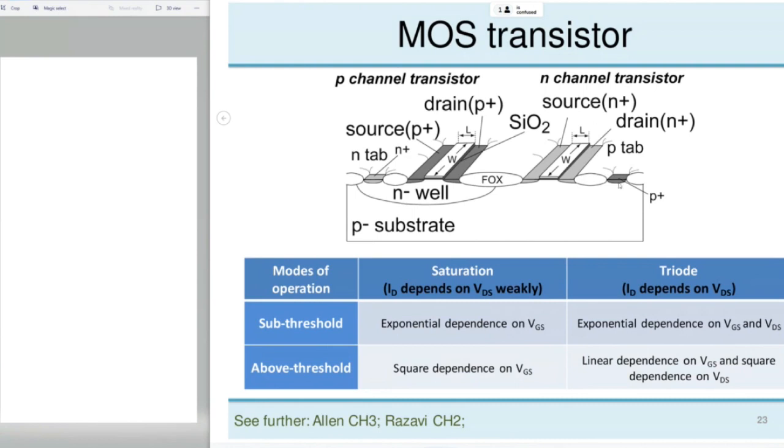And you see that it needs to be always the lowest potential in our solution, so that this parasitic capacitance, this parasitic diode that we have here between the drain or the source area, which is an N plus area, and the P substrate is reverse biased. So this parasitic diode should always be reverse biased and not turned on. Otherwise, there will be big currents and it will melt our device.